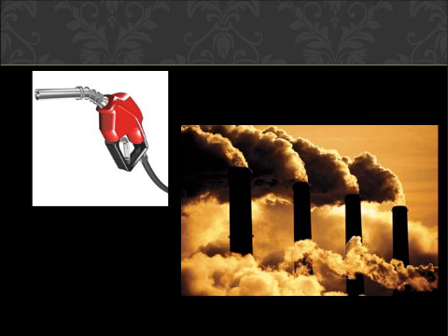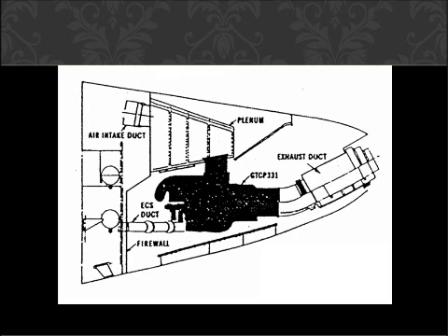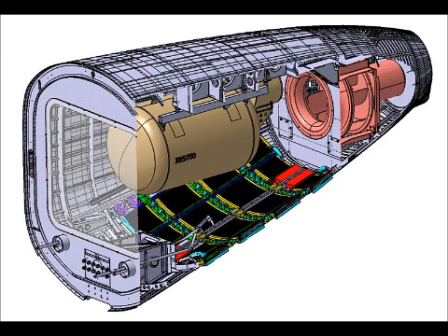Two main advantages of the SOFC APU are the reduction in fuel consumption and nitrous oxide and carbon dioxide emission. Traditional turbine powered APU is used to provide power for engine startup while the aircraft is on ground. SOFC APU, on the other hand, can be used to supply electrical power both while the plane is on ground and in flight efficiently. This is because the SOFC APU has higher fuel efficiency for generating electricity as compared to traditional turbine APU and the aircraft's turbofan engine.